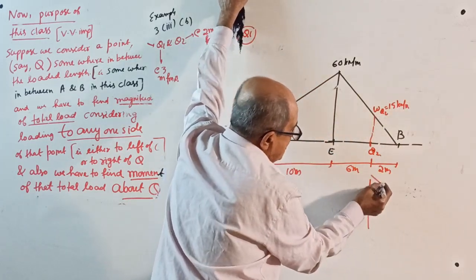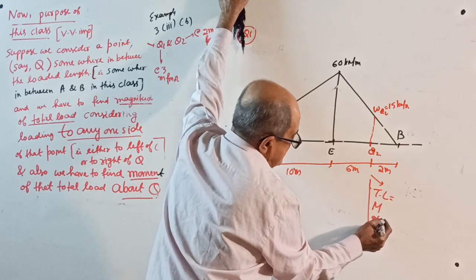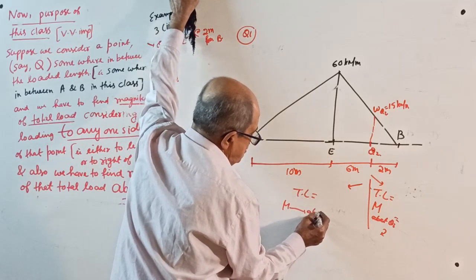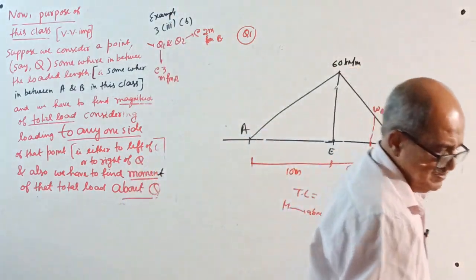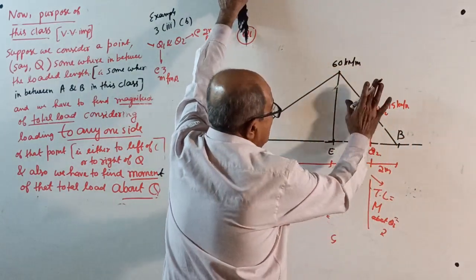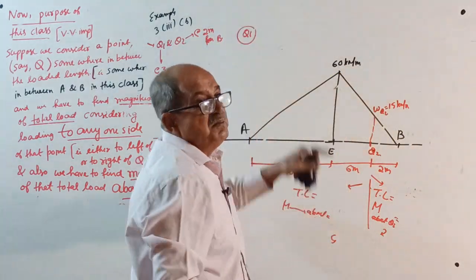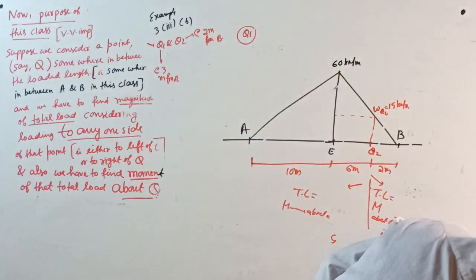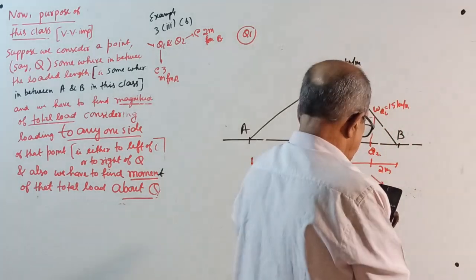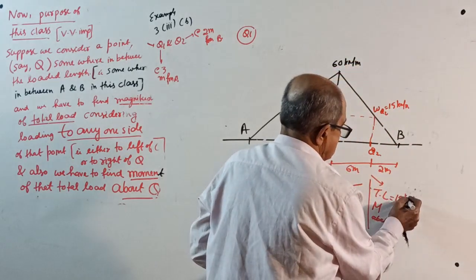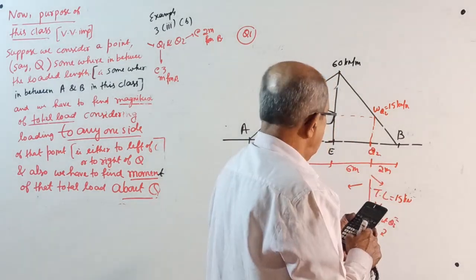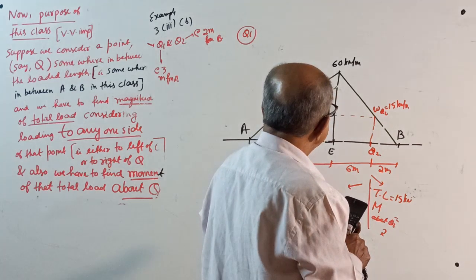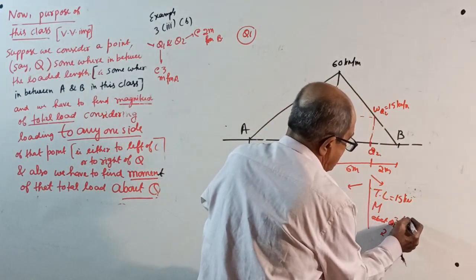Okay, now answer. If you look right side, total load and moment about Q2 is clockwise. If you look left side, the answer will be anti-clockwise. This time you will get a trapezium here. When you look left side, if you can manage trapezium, take trapezium, or you know it, rectangle, triangle. So total load, that side is half into 2 into 15, 15 kilonewton. Moment is half into 2 into 15 into 1 by 3 of 2, 10 kilonewton meter.